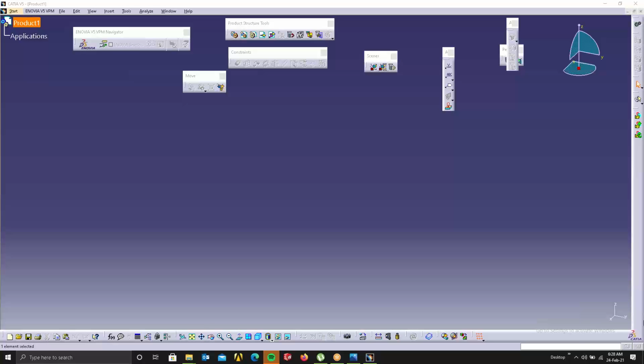If you don't mention it, sometimes it will be difficult to achieve that flatness. It is very difficult to achieve if the product size is 600 by 300 or 900 by 300. When the product is very long, that's when it's very difficult to achieve the flatness, because when you clamp it, there will be a bend anyway. If it is a small part, 200 by 200 or 500 by 500, though 500 is also difficult, then it's not a big deal. It's easy to achieve the flatness.